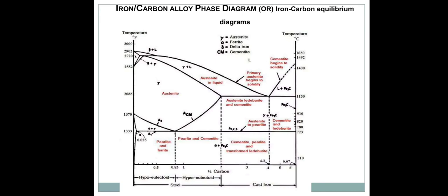Bainite. Here we can see cementite lying sideways below and above the bainitic structures in this curve. Bainite is a decomposition product of austenite consisting of an aggregate of ferrite and carbide. Bainite obtained by transformation at higher temperature has a feathery structure.